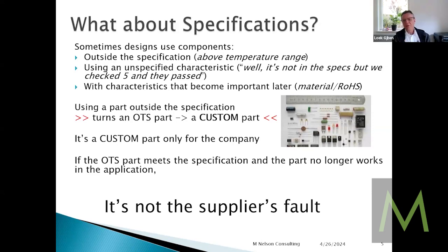Yeah, but Bob, if you have a new part, then your supplier is supposed to inform you that it's going obsolete. And normally what they do is they give you a last time buy option, and then you have to calculate how much you need for the upcoming time, and you buy it. Or the supplier says, I have an alternative part, and they give it to you, you test it, and you say, okay, it works in my system. Let's do a redesign, or I change my bill of materials with the new part, and it works as good as the old one. That's normally how it goes.